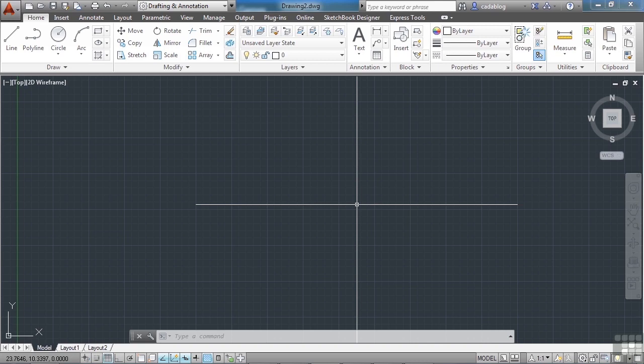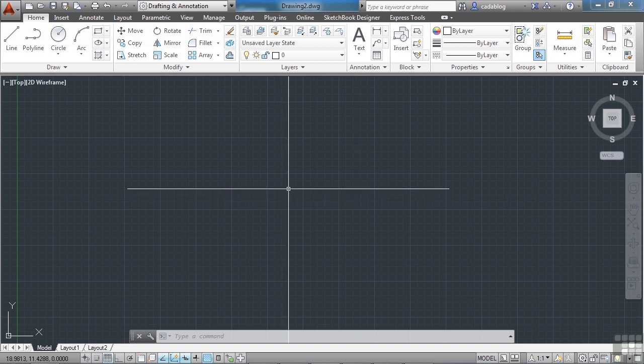But viewports and Paperspace give you a view of your model. Viewports and model space do that too, but it's not for drawing creation purposes. It's for modeling purposes. Model space is where your data goes, your drawing, your information. Paperspace is where your drawing information goes, dimensions, notes, title blocks, etc. Viewports and model space give you multiple perspectives of the same model. This allows you to work from different perspectives simultaneously. It's very useful when modeling a 3D object, or when working on very large projects.